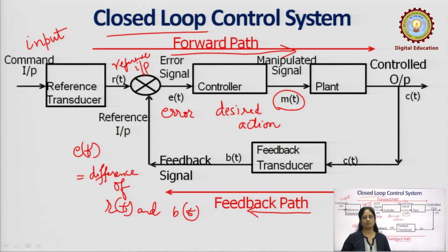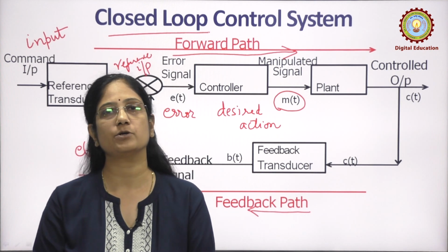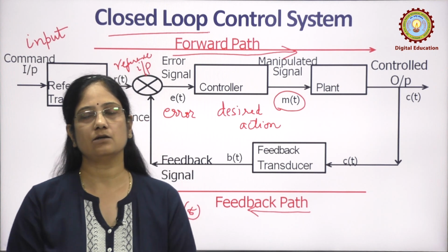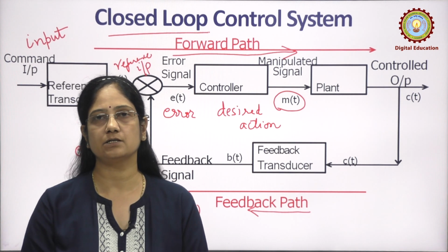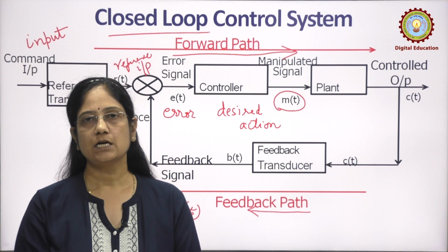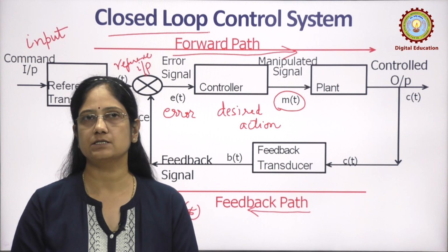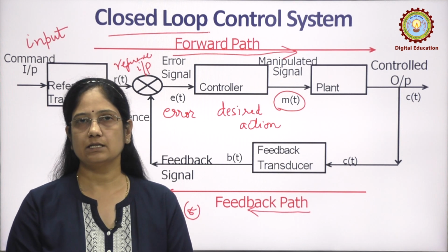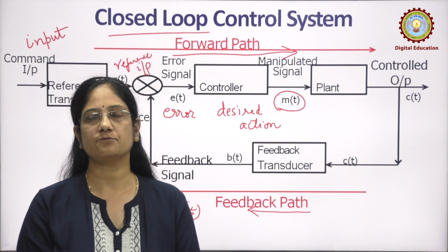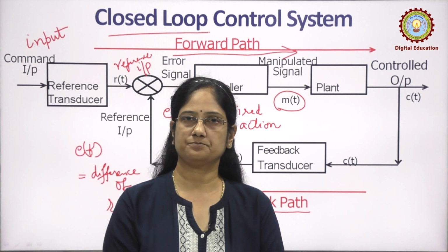Okay. So, there are many components in comparison to the open loop control system. The number of components has increased here. We are now comparing the output signal with the desired response, and if there is a difference, that error is fed to the controller, and whether a proportional, an integral or a differential signal is sent to the plant again, and then the output is again compared. So, this process which involves a feedback path all comes under the category of closed loop control system.